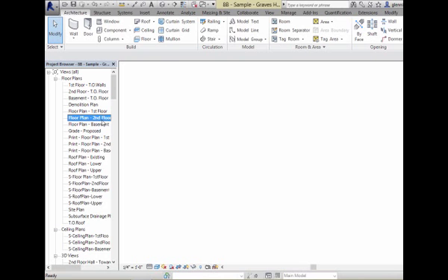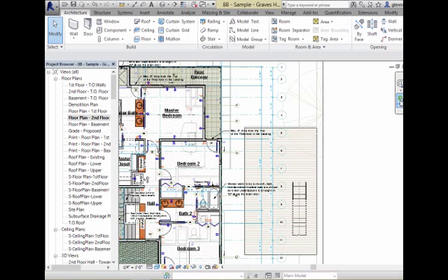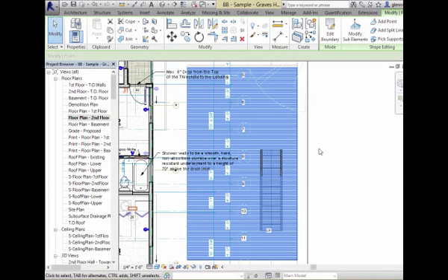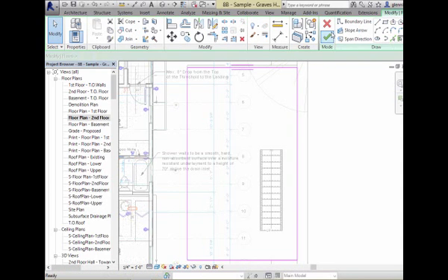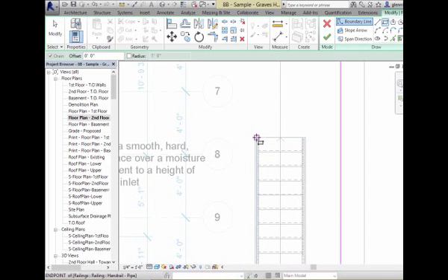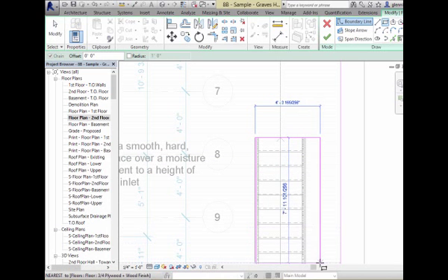What I'd like to do is actually go up to the second floor. You can sort of see the ghost of the stair right there. And what I'm going to do is go through and edit that floor. So I'll choose the floor and edit its boundary. Now we're ready to go ahead and start just cutting a hole or putting an interior boundary in there. And that's kind of worked out okay. I can be very precise or a little loose, however you want. I'm just going to make a big old rectangle wrapping around here.